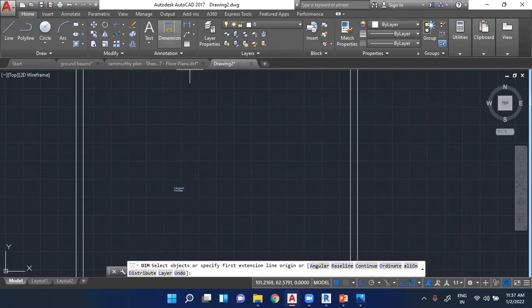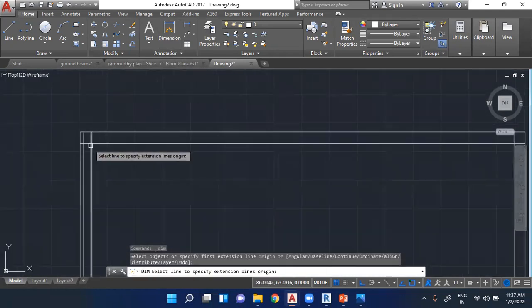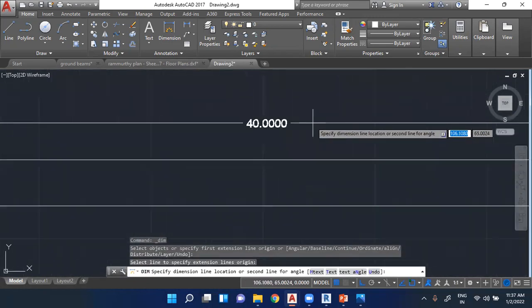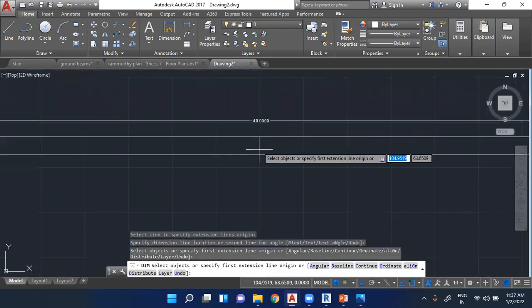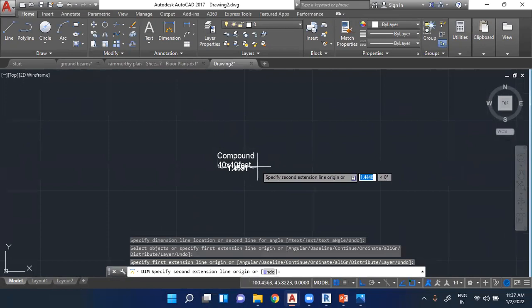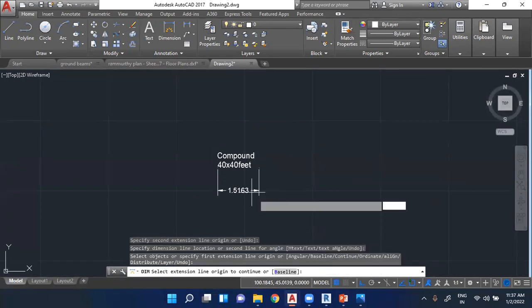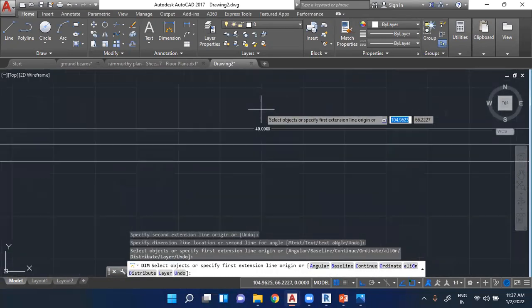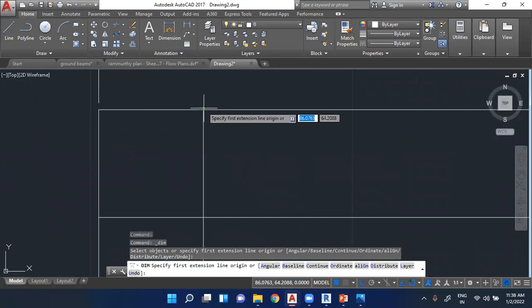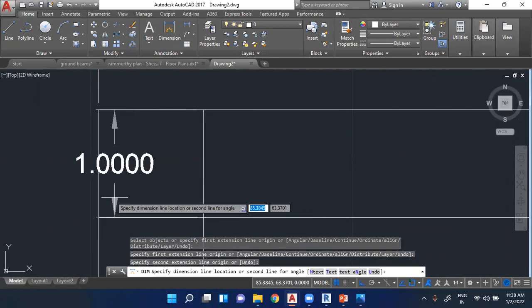The next option is dimensions. With the dimensions tool, I can show the dimension of the lines or whatever I have here. Even the text dimension I can display here by clicking two lines, even the line dimension, and whatever dimension I want to specify on the drawing for clear understanding, I can click and show here.